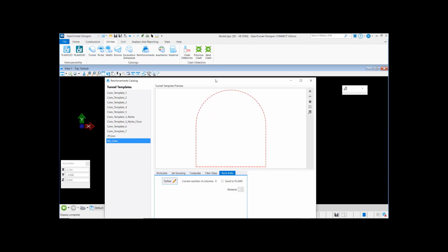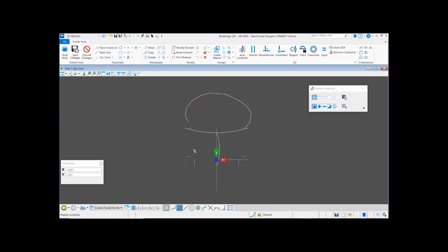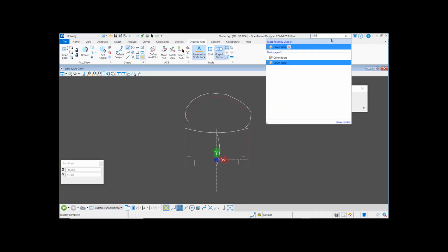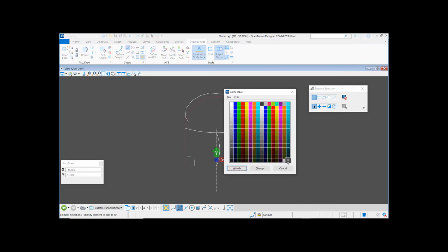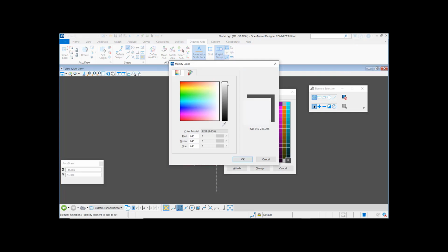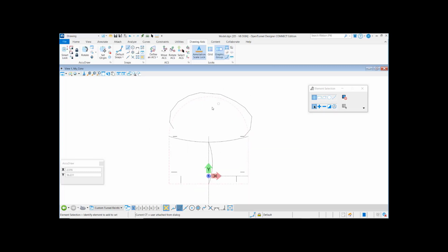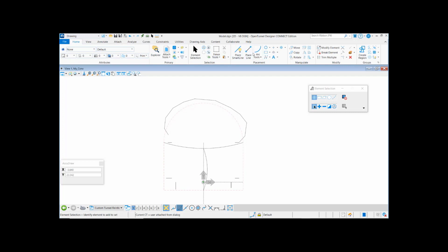For this cross section, I can define also rock bolts. So rock bolts are placed in different places. Here I will put only in the top, for instance. So the same, when I define them, create a 2D temporary space where it will plot the cross section, change the background color to 0. And now I will draw the bolt. So the bolts are represented by a line. So this line will be, I will put a bolt at the center part of the top of my excavation.